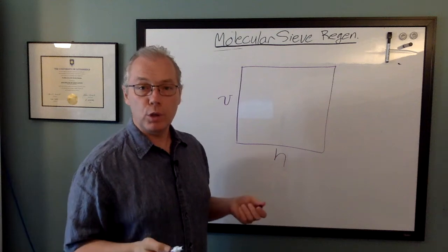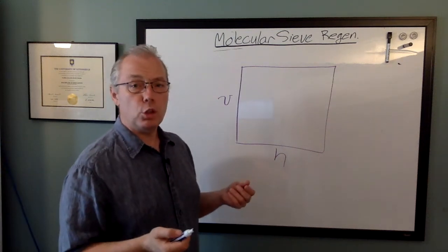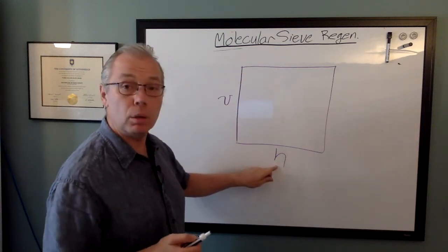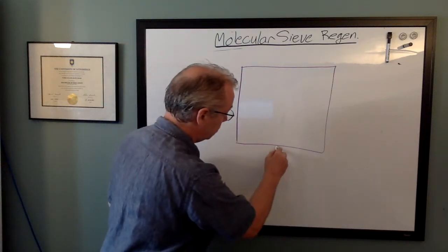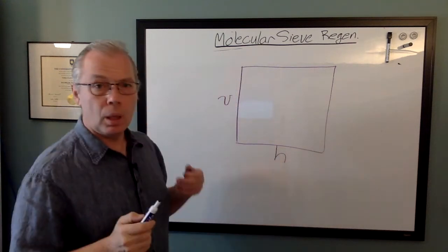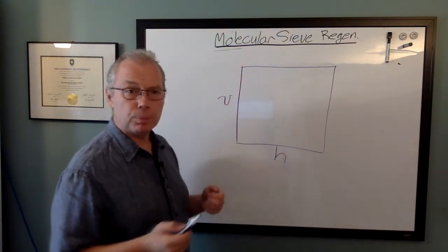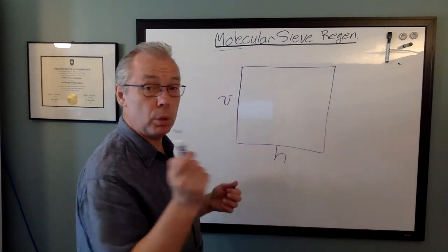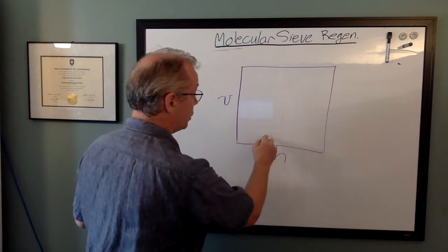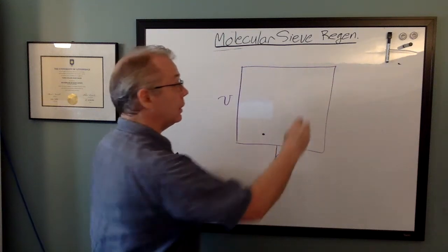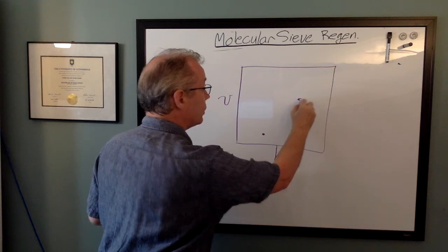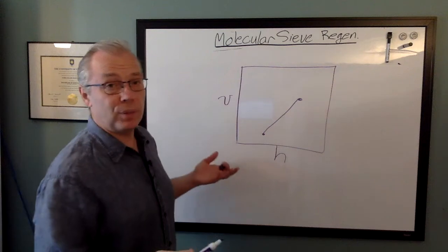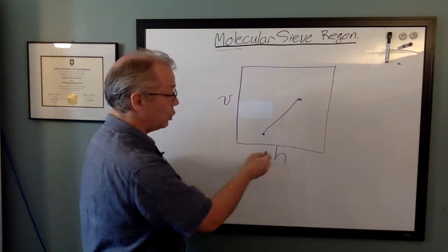First, we need an equation of state. And this is the relationship between specific volume and the enthalpy of the fluid. Now, a really simple equation of state is linear. And we know 2 points exactly. We know the specific volume of a saturated liquid, we know the specific volume of a saturated vapor, and between the two, we know that the specific volume of a two-phase mixture is a linear function of enthalpy.